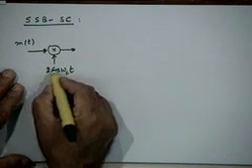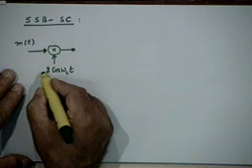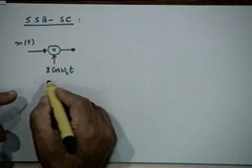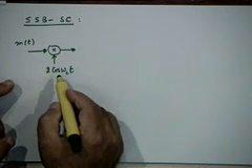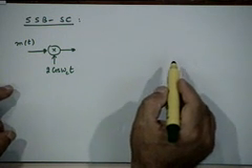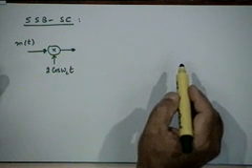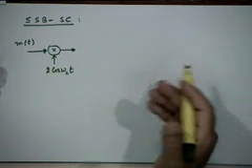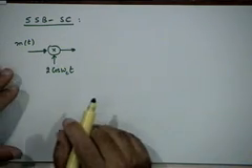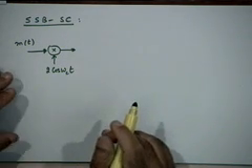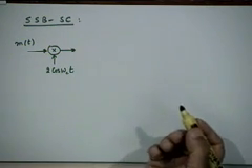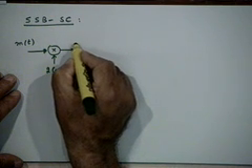You will notice that I put different constants in different models. Sometimes I put root 2 cosine omega_c t, sometimes I put 2 cosine omega_c t. Basically the idea is that I should put a constant in such a manner that the input power to the receiver S_I in every case is the expected value of m squared. I just want to keep the same signal power coming into the receiver input, so as to keep the treatment uniform. It is a matter of scaling, nothing else. It does not affect the results in any way. Even if you did not do this, you would still get the same answers. The SNR results will be the same.